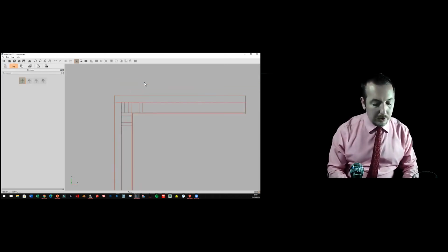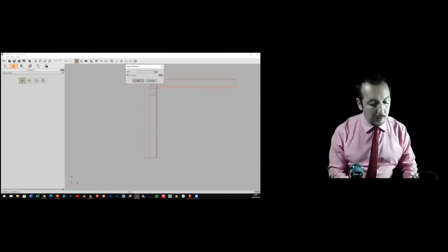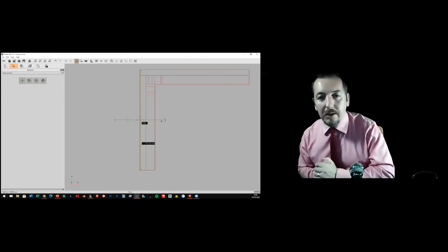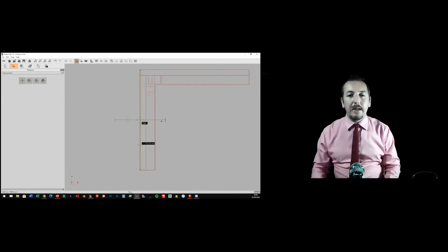I just want to clarify wall 1, or at least highlight what I'm doing. Now, that stretchy thing that I just put in there is called a flanking element. And basically what it's saying is, I'm taking the U value through here over this straight length.